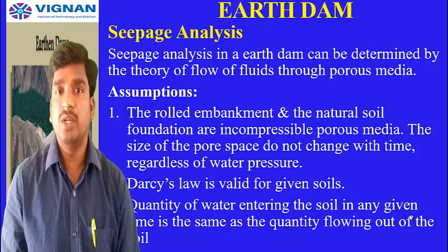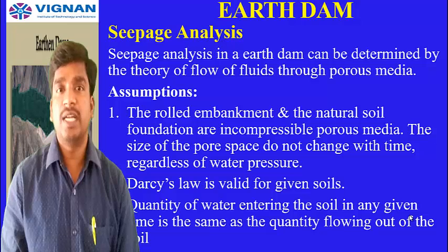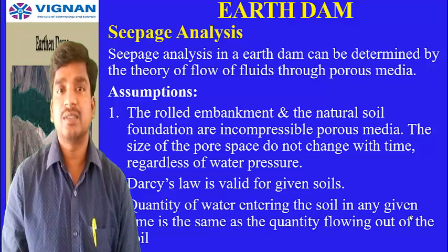Seepage causes many failures, because seepage from upstream to downstream creates pore pressure in the body of the dam, and that creates many problems.